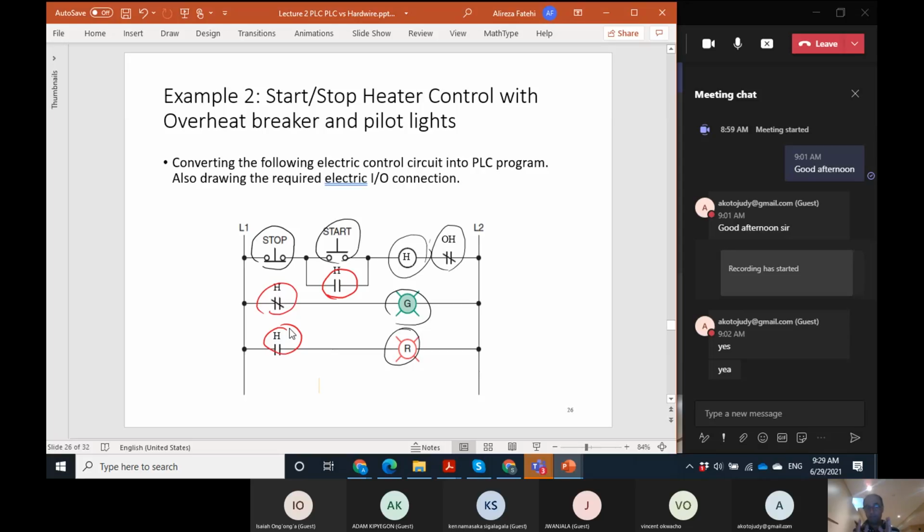Most probably, many of these types of devices might be just the auxiliary contacts of them, or some separate, extra relays, contactors, and the like. We just use them because we want to implement some logic. Most probably, we don't need them anymore. All of them can be implemented by the internal memory in the PLC. We don't need them, but we should check.